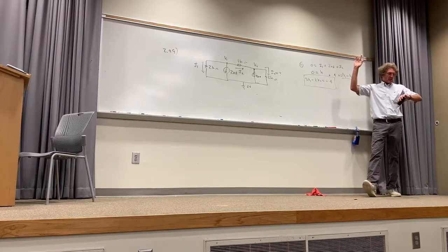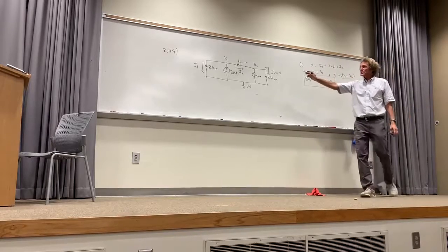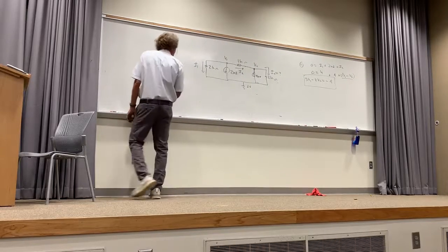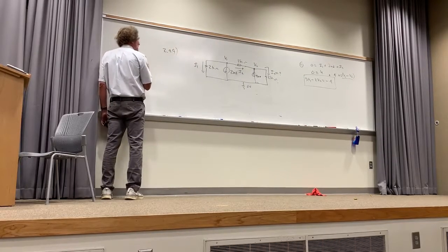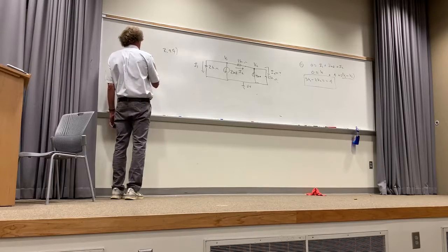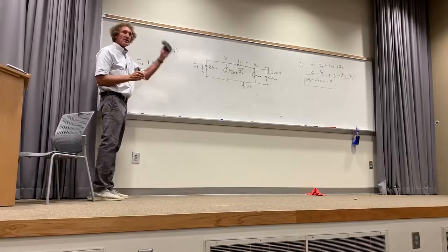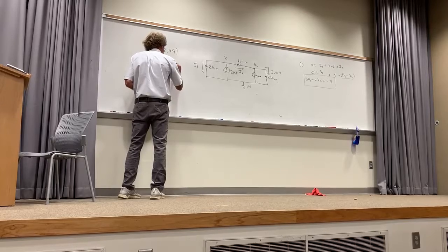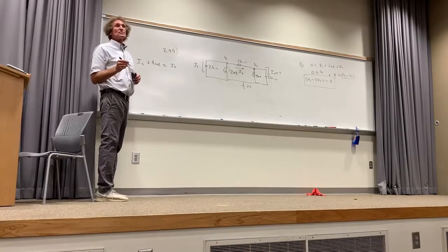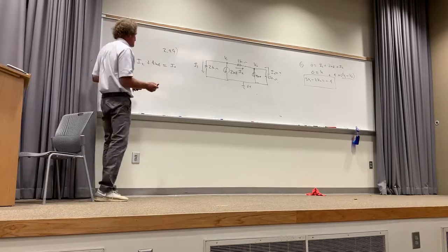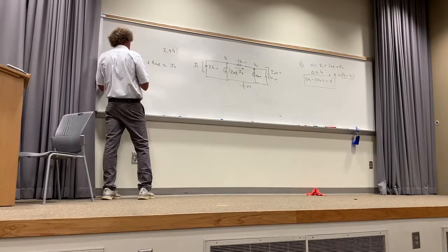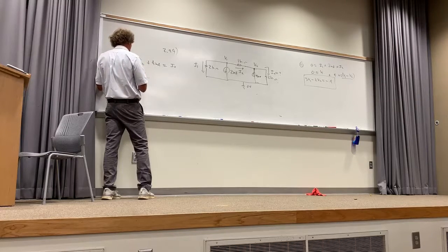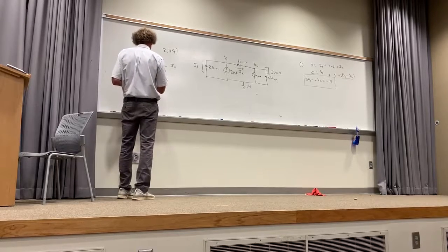Let me finish my train of thought here before you blow out of here, all right? Now what about the next one right here? Go ahead and tell me what currents go into that node. I2, and plus 4 milliamps. You all see the 4 milliamps is going into it? What comes out? Now replace these with the unknown voltages and the known voltages. What is I2? It's V1 minus V2 over 1K.